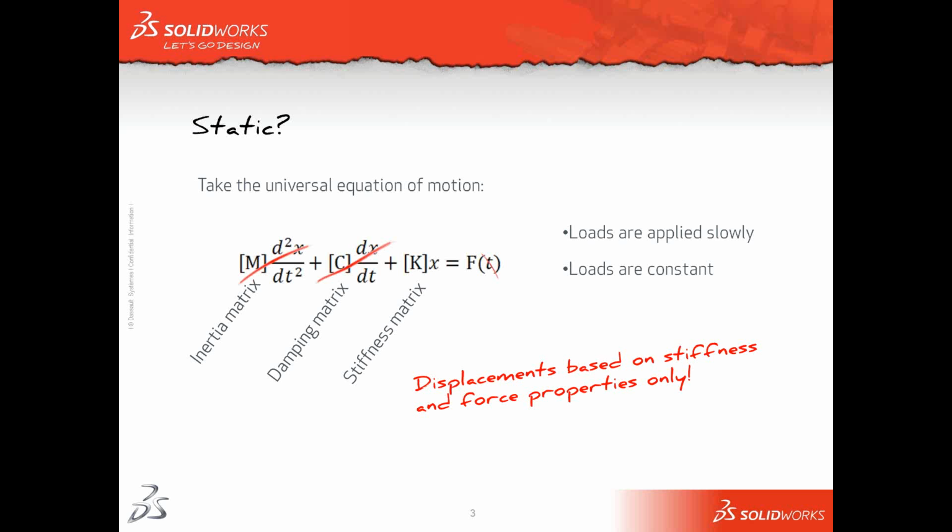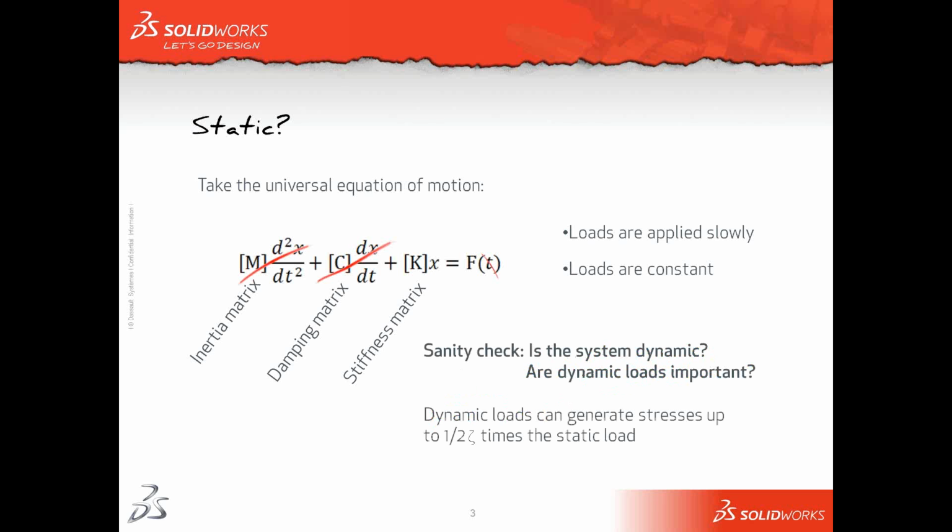Because when we say static, we are ignoring some of the dynamic terms. Now, in some situations, that's absolutely fine. If we are placing a load upon a table, that's fine. We're not expecting any dynamic loads. But if, for instance, we look at our model and we are expecting dynamic loads, we need to assess whether the static assumption is still okay.